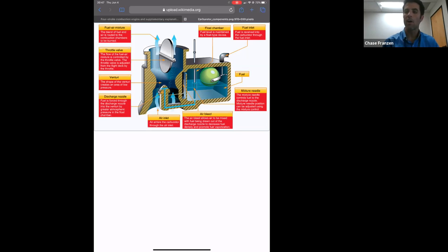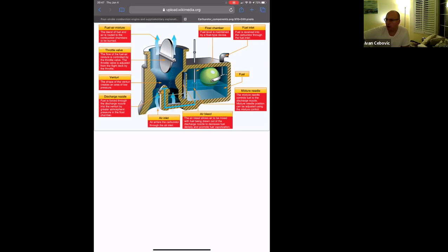Our aircraft uses 100 low lead fuel. We expect that to be blue in color and again, not contain any water inside of the fuel. It's important to sump from both wings as well as from the lowest point in the engine, the gascolator. What can we expect at the lowest point? Why is it on the lowest point? Because the water will be down there. The water kind of sinks, right? Yeah, it sinks.